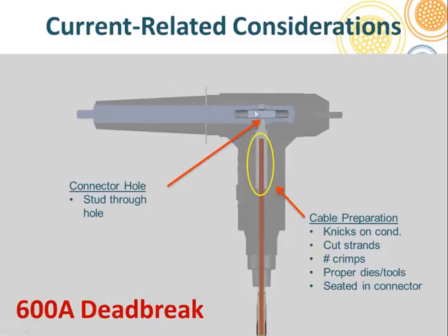Now he greases the 600 amp bushing, and now he starts to move the elbow housing over to put it onto the bushing. And it's just a little bit short. The cable's just a little bit short. So he lifts up on the elbow, figuring that he's lifting everything up. Unfortunately, what happens is the elbow slides off the cable adapter, and the hole only has to slide down 5/8 of an inch, and he puts the insulating plug through with the stud, and he misses the hole.